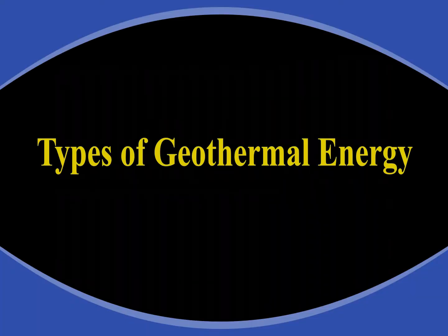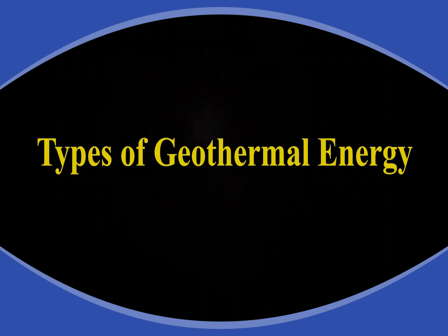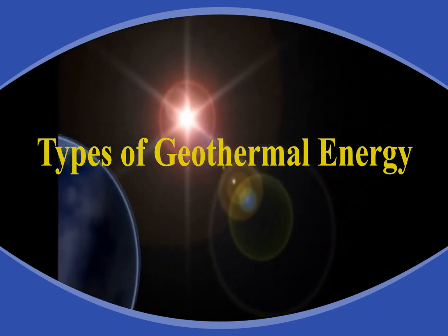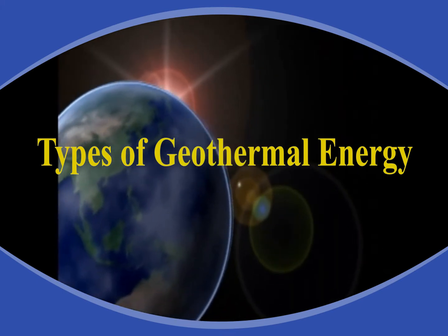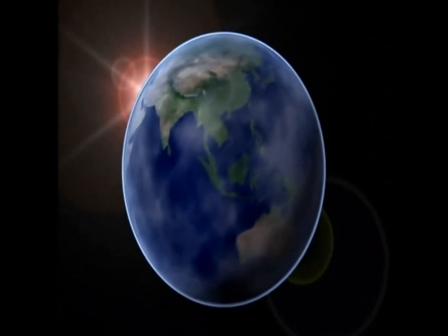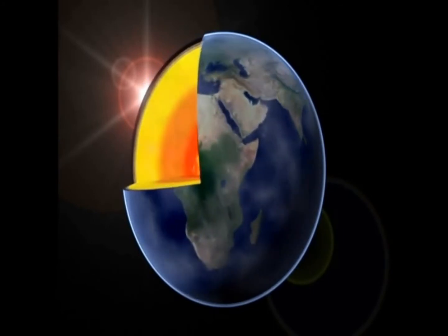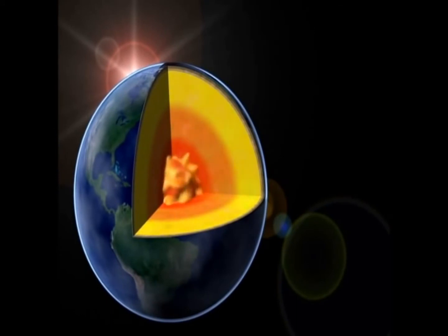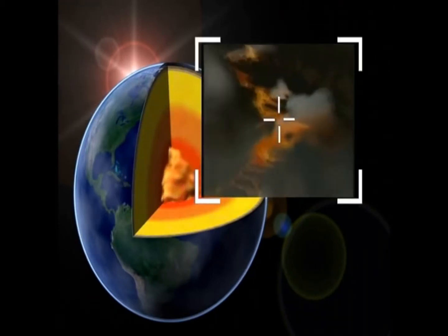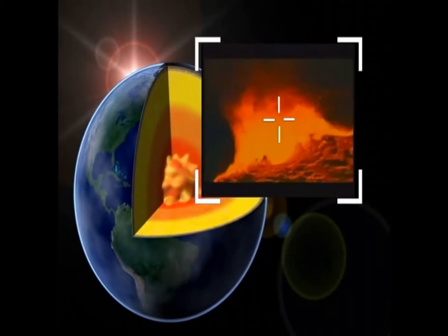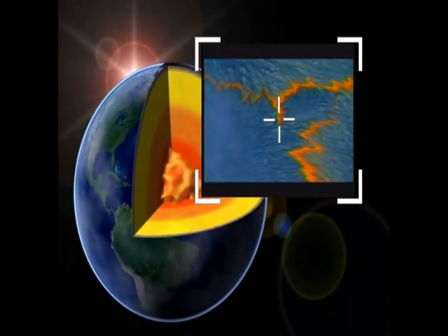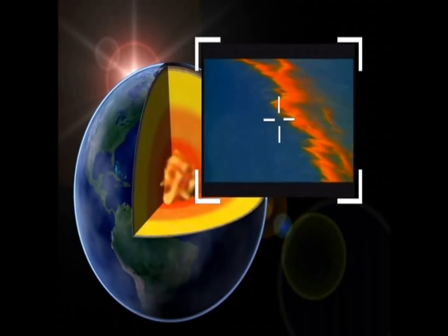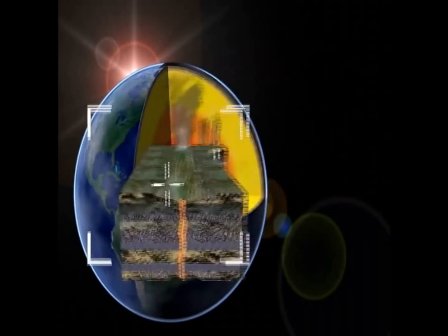We have to know that three geothermal resources can be identified according to their temperatures. First, high temperature, over 150 degrees. Water and steam are obtained at high pressures and can be used to generate electricity. Medium-low temperature, between 150 degrees and 30 degrees, can be used for heating purposes and hot water, electricity production, industries, greenhouses and farms. Low temperature, below 30 degrees, is used for air conditioning, cooling and hot water for houses.